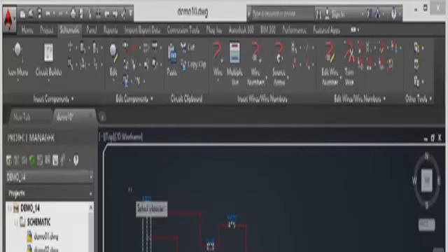Now we want to select the objects in the drawing itself. We need a base point, so we pick a point in the drawing. Make sure your object snaps are on, and then you can snap to a corner of, say, that connector there, which is what we're going to use for our W block. Then I need to select the objects that make up the actual W block itself. So I'm going to click on the Select Objects button here, and then I'm going to select everything that makes up my circuit. Now I'm doing a crossing selection there, so as I cross the bottom of that connector, it still gets selected like that.